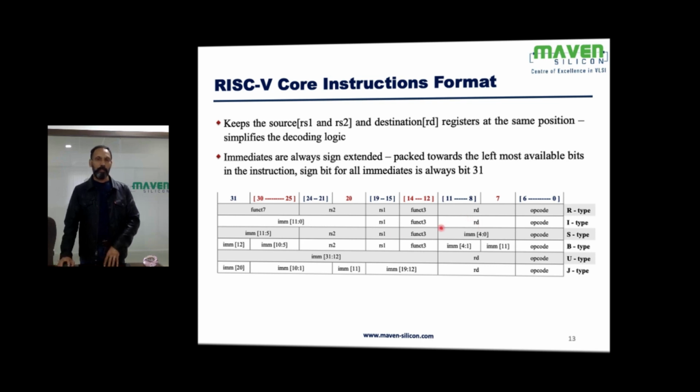In this case, we need to make this constant 32 bits because RS1 has a 32-bit value. So the operation is going to happen between the 32-bit constant and the 32-bit value of RS1. So we need to sign extend this immediate value.